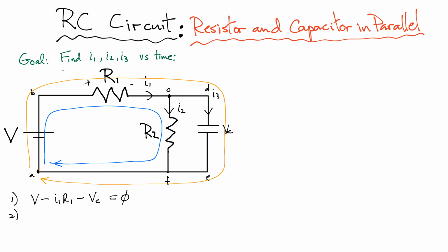The first two terms are exactly the same because I cross a battery and I cross the resistor, so those haven't changed. Now the next thing I do is cross the resistor R2 in that middle branch, so I'm going to get a voltage drop. I'm crossing the resistor in the same direction as the current, I2 R2. And that's it. I go back to where I started. It has to be equal to 0.